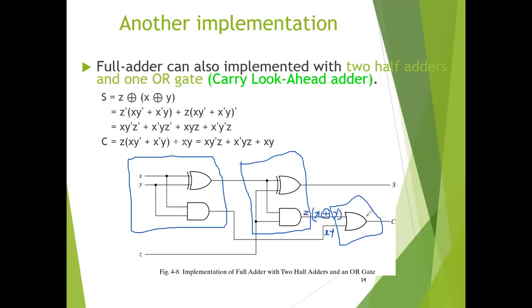And that output will be added with this thing, and we will get our carry output for the carry look ahead adder. This is also known as the carry look ahead, and this is the implementation of a full adder with two half adders and an OR gate.